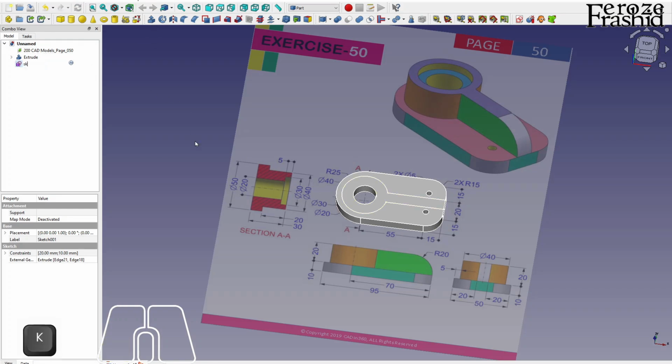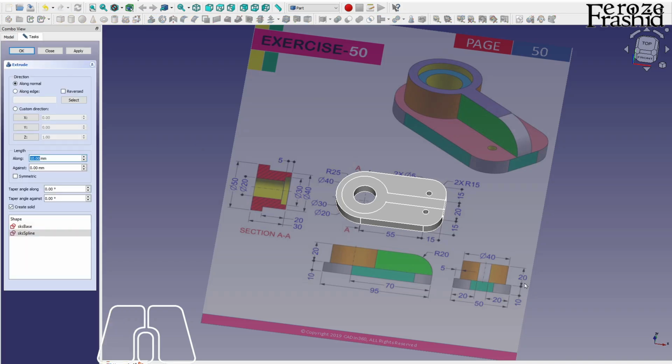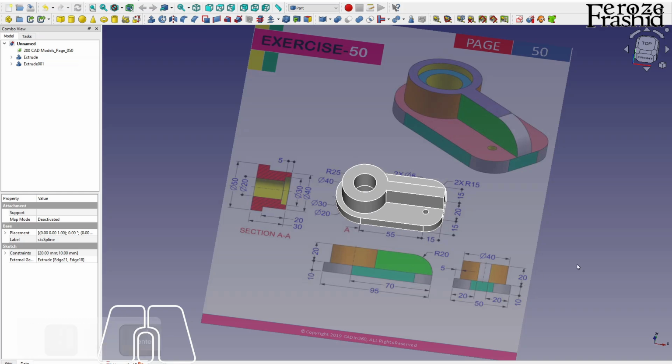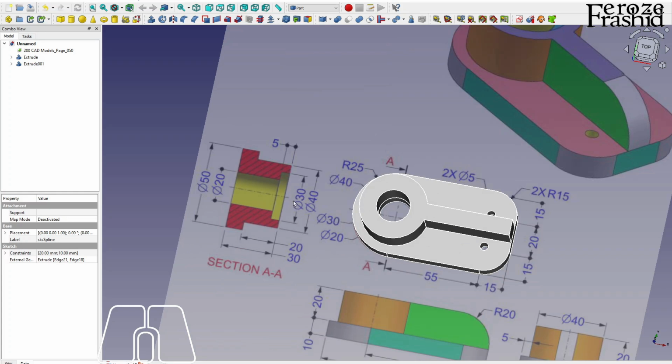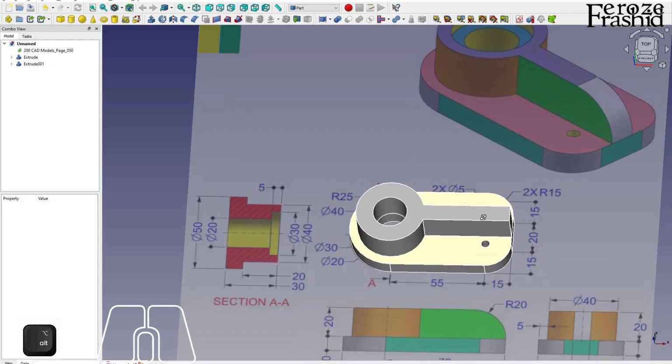I'm going to say sketch line. That will give me an idea. I want to extrude that for 20 total. Alright, now there is an inner hole that we'll have to make, which is diameter 30 and it goes down 5, right? And I can do that 2 ways.